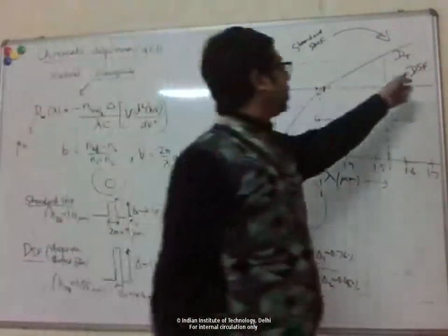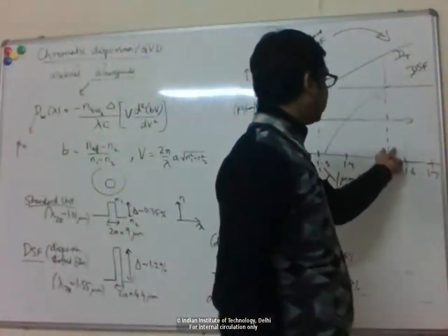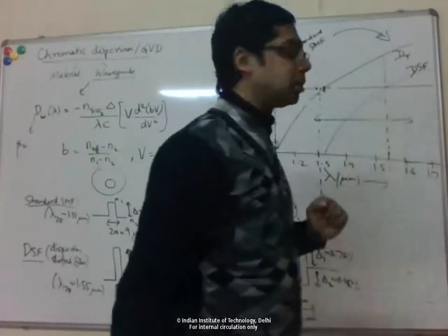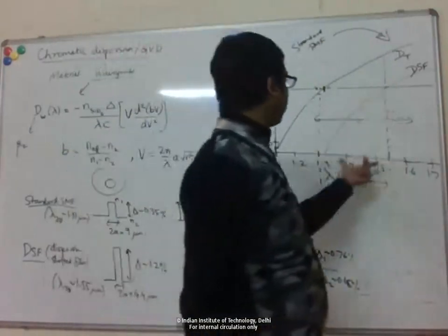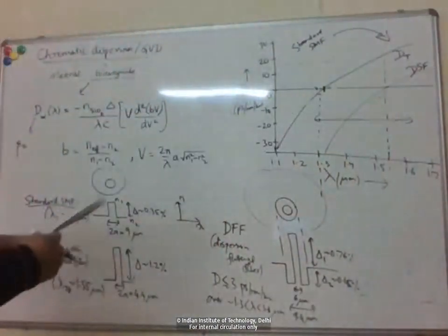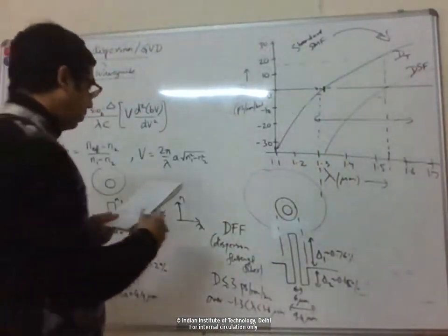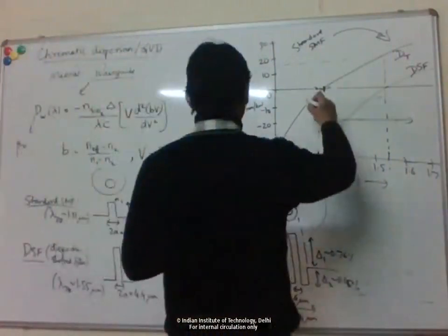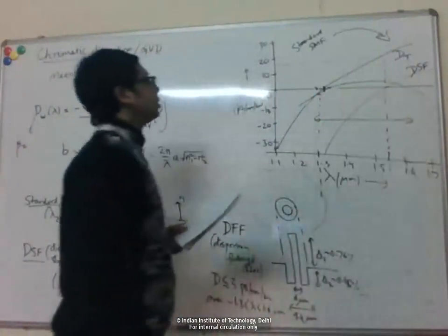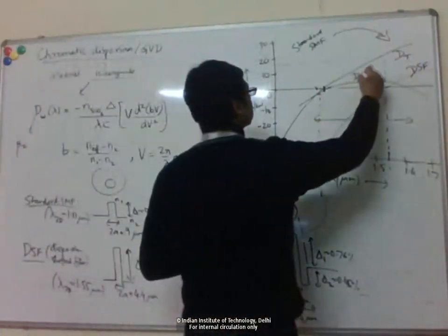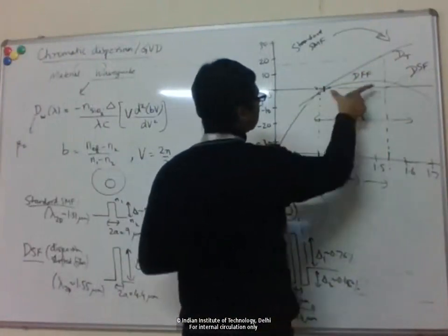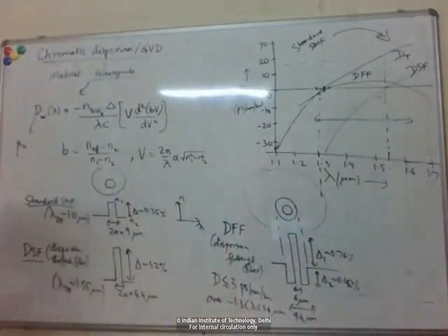Right, so this is useful if, let's say, you are using the C-band wavelengths around 1550 nanometer, then you can get both minimum loss and minimum dispersion. But it's still not suitable for wideband applications if you want to use the entire telecom range. So if you look at the dispersion flattened fiber, that looks like this. Okay, so it has a very low value of dispersion over this entire band.